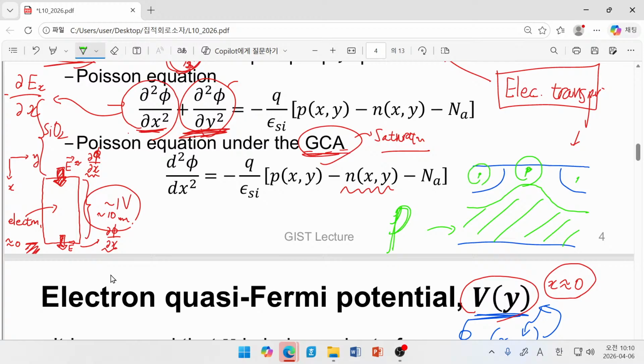It is certain that even compared with your depleted channel region, your hole density here is even lower. For example, if your doping density is 10 to the 20 per cubic centimeter, then what will be your hole density? Your hole density will be just 1 per cubic centimeter for your source, and of course for your drain.